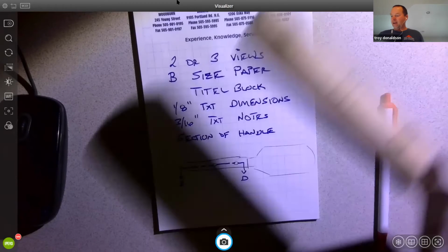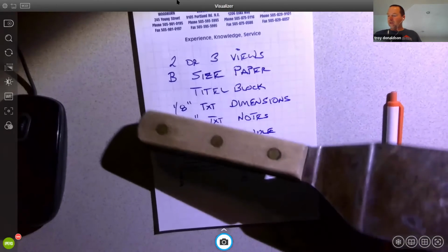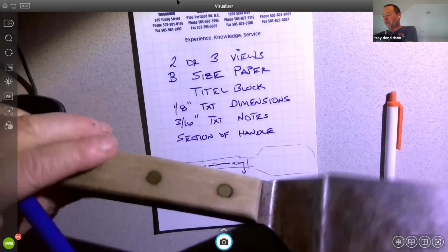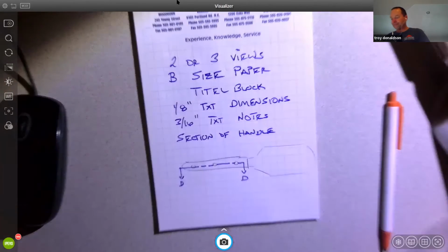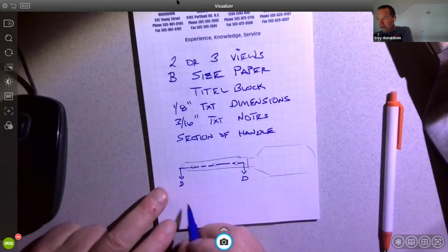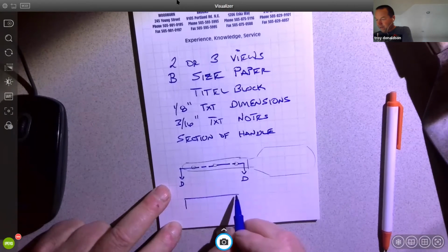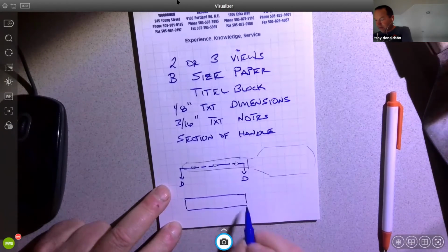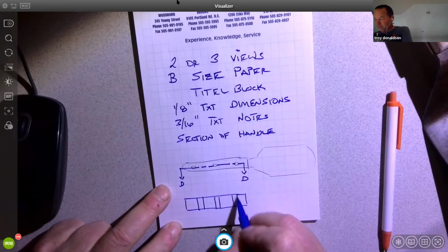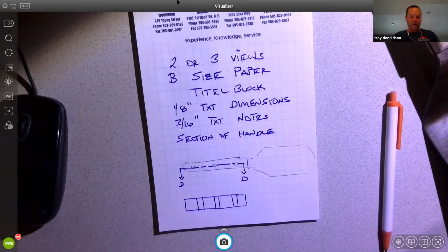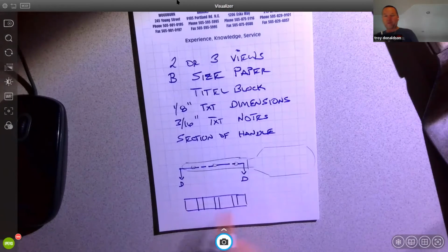So on this thing, there are no holes. It's filled with brass plugs. That's what it looks like, right? So when you cut through that, it's going to create a section view, something like this. And then it's going to have these plugs in it. I'm kind of overemphasizing those, but, and then so all of this would get hatched.